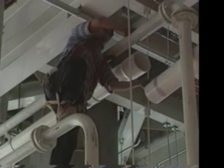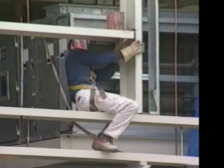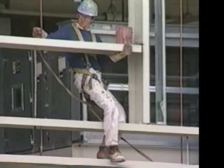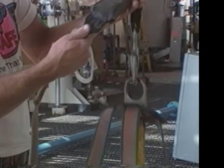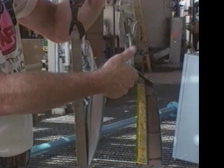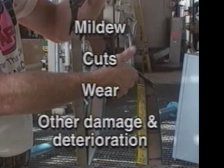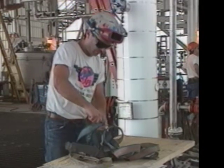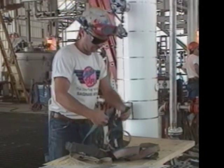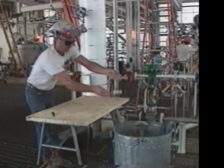By using the proper fall protection device for a particular situation, you have taken a significant step in preventing falls. However, you are unprotected if your equipment fails. Before each use, a competent person must inspect fall protection devices. All items must be inspected for mildew, cuts, wear, and other damage and deterioration. Defective components must be removed from service immediately, and should be tagged or marked as unusable. The items should be destroyed if a qualified technician cannot make repairs.